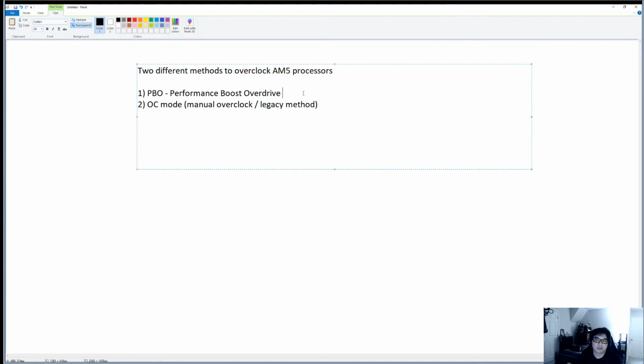You don't want to reduce the voltage, you want to add more voltage. When people ask me about undervolting, it's the opposite of overclocking. If you're going to undervolt, you're essentially dialing back the power or the voltage available to the processor. At that point, you're trying to get clock stretch, which is a term that AMD uses internally when it comes to overclocking on the processor. Essentially, with undervolting, you're trying to see what is the limit in the silicon.